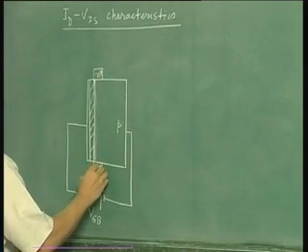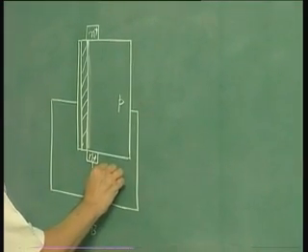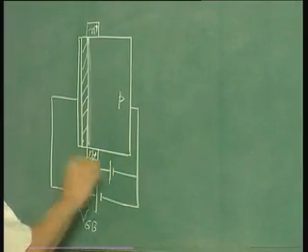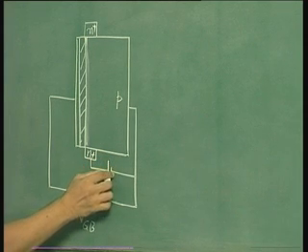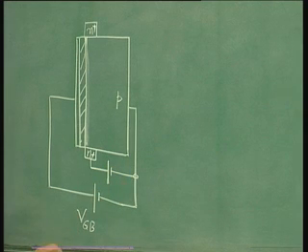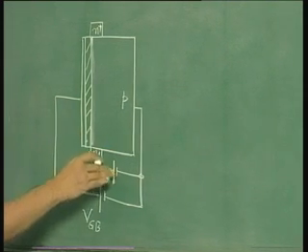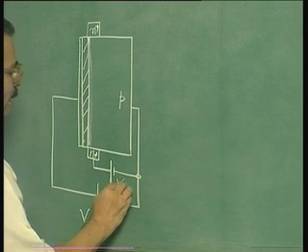Then we apply a voltage to the source with respect to bulk. Now in our characteristics this particular voltage has been shown to be 0, but that is the characteristics on the slide, but here we will have an equation which will also take into account this voltage, then we will set this voltage equal to 0 to see how the equation simplifies. So this is VSB.